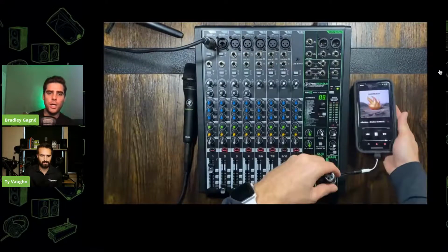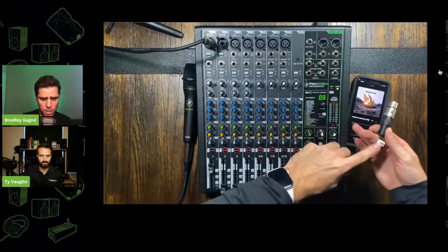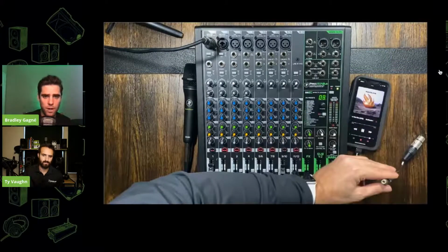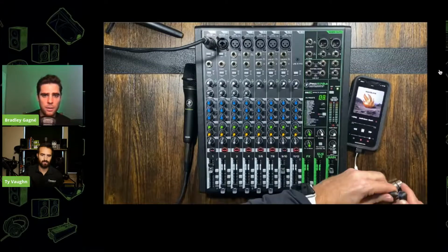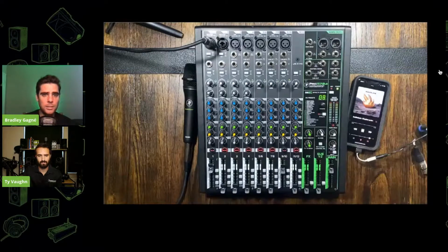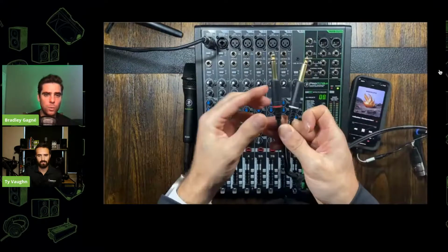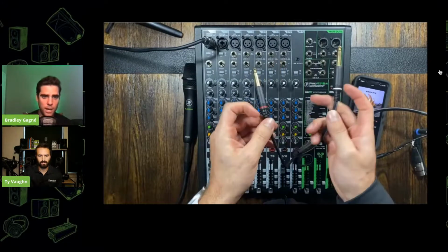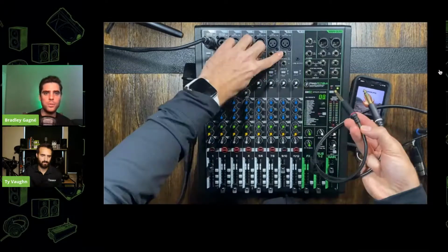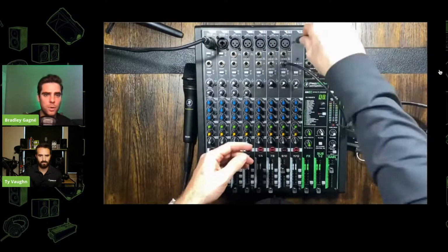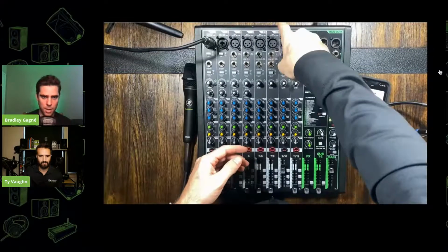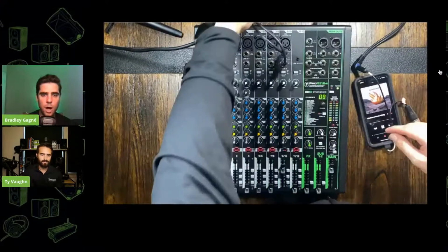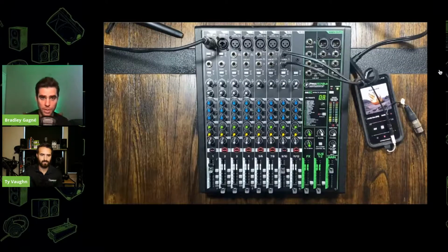And we got to get the audio out of the phone. So we have our mic and then we have our speaker output. So we're going to take that other cable, the 3.5 millimeter stereo 1/8 inch jack, plug out of the speaker output. And then it's a dual 1/4 inch cable. Right is always red. So remember that. And then on the 1/4 inch inputs on our mixer, we're going to bring that sound into the mixer and we're going to plug in left and right is red. So we match that up. That's our stereo connection. That's going to take the audio out of the phone back into the mixer so we can actually listen to the caller.